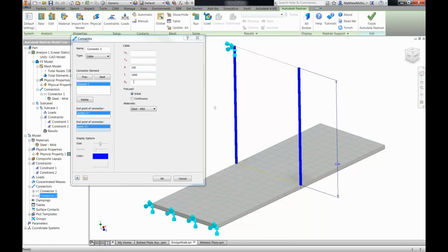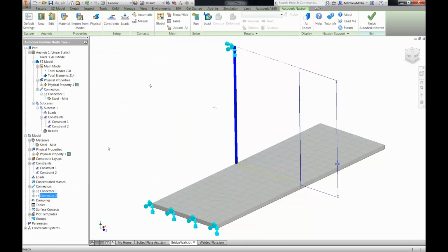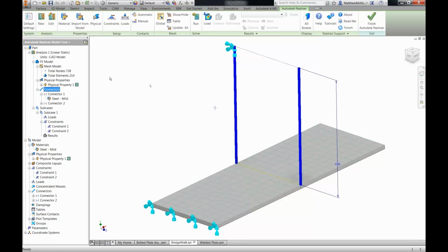You'll note that any properties that I've associated with it are then retained. But the one thing that you do need to realize is that when I'm copying and pasting features down in the model area, it doesn't automatically add them to the analysis type that's being run. So I do need to drag that up and add it to the analysis that we're conducting.